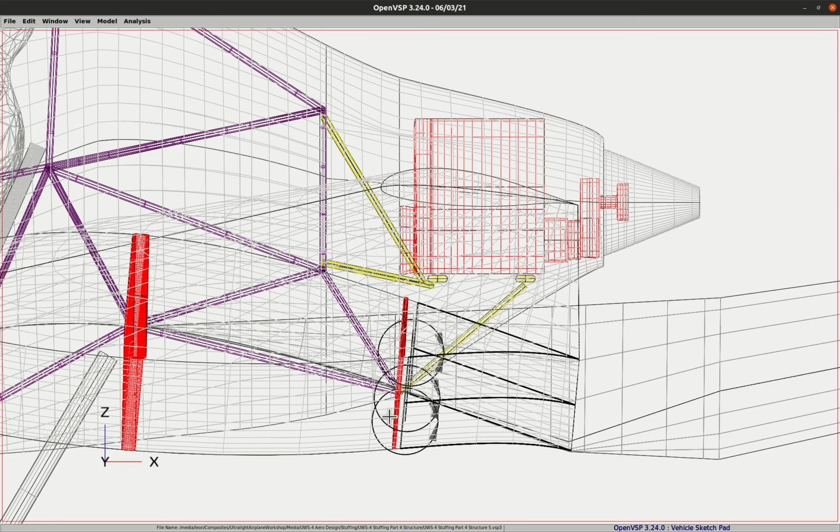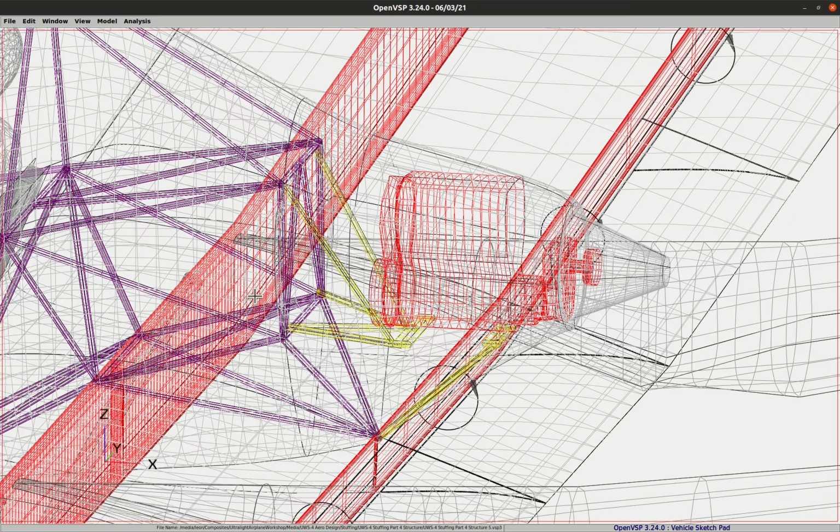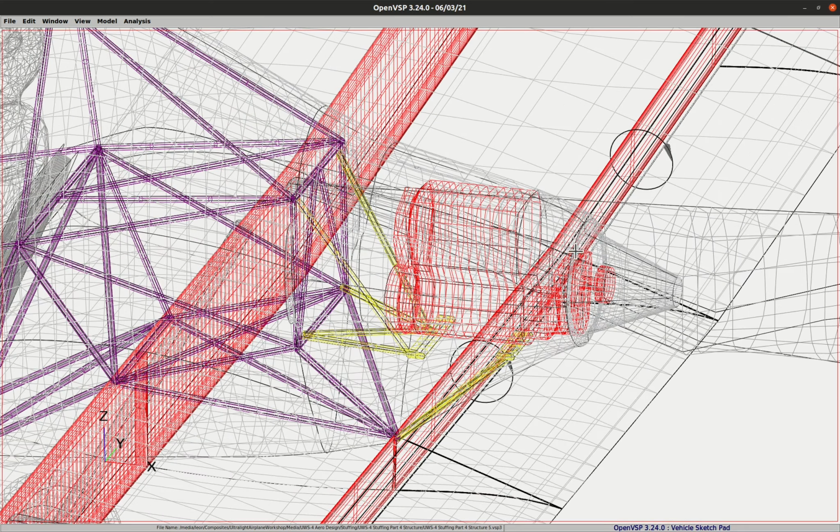And of course, this also handles vertical load from the front of the engine. This back here handles vertical load from the back of the engine. Let's rotate a little bit. Now this structure back here handles any torsional loads. I may have to add one more cross diagonal in here to handle some torsional loads and side-to-side loads. Now this one down here can handle plenty of side-to-side loads. I think I'll make it so that this one will have a diagonal and handle a little more side-to-side.